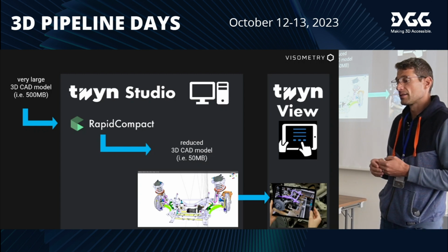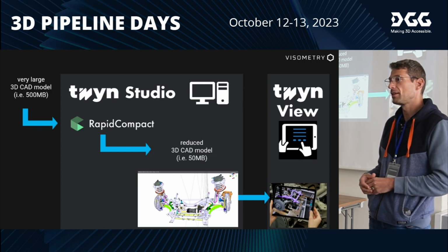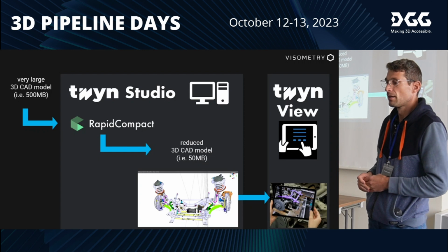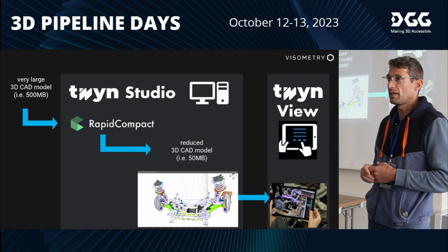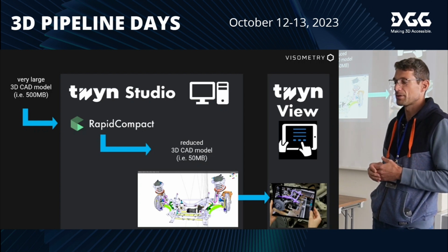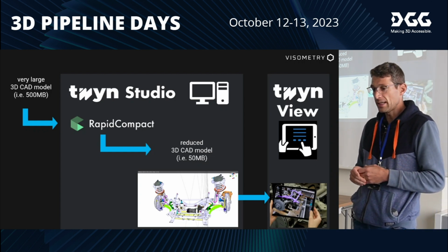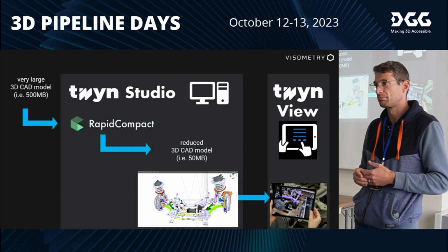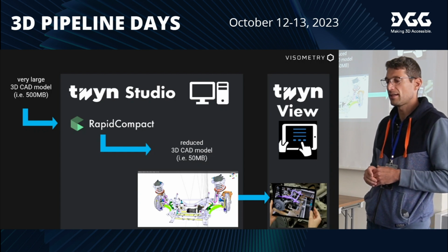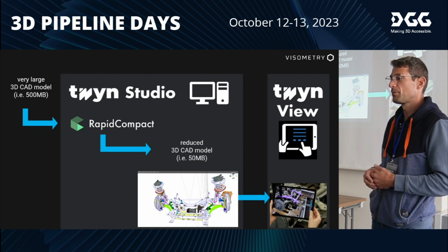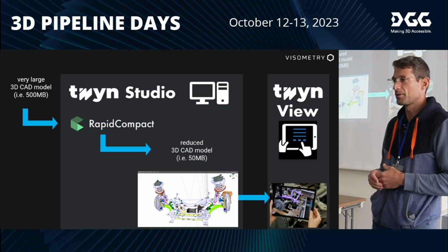And for tracking, it's mostly only necessary that you see the 3D data which is really visible. So every hidden geometry is not needed in many cases. This also helps to really reduce the geometry to a very compact format. And then, of course, it makes it possible, if you have really large original 3D CAD data, to put it into a representation which can be easily deployed on an iPad with way less of the original data size.